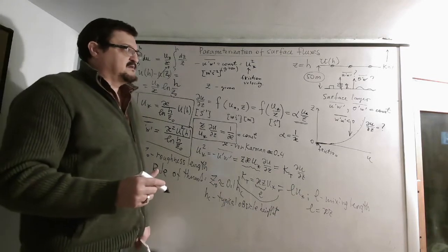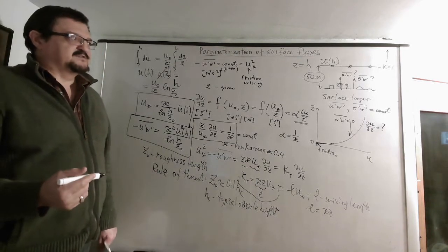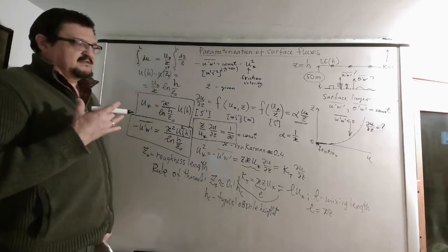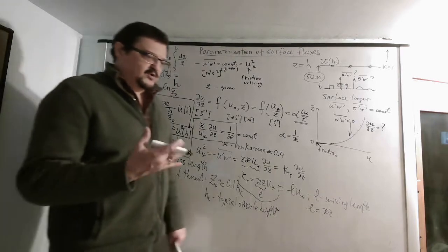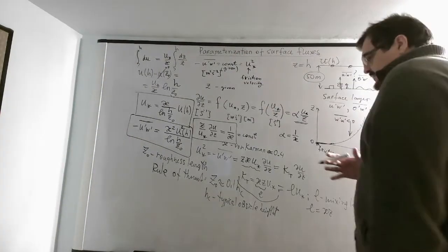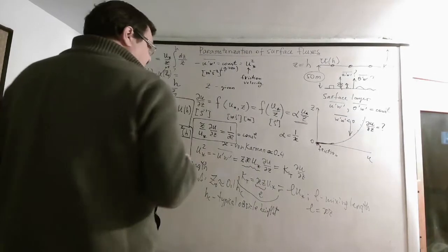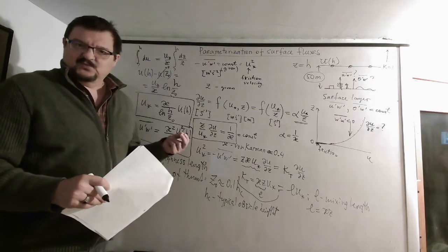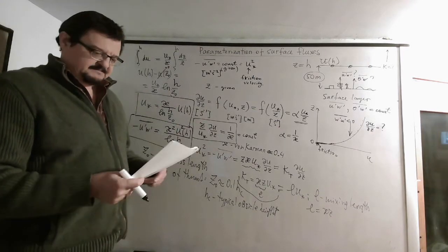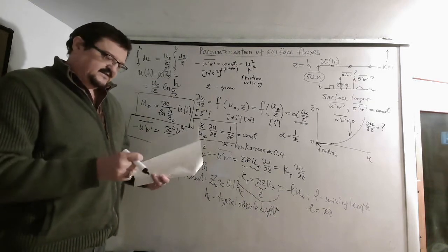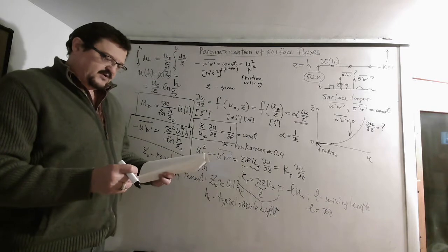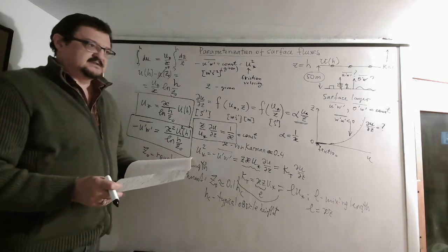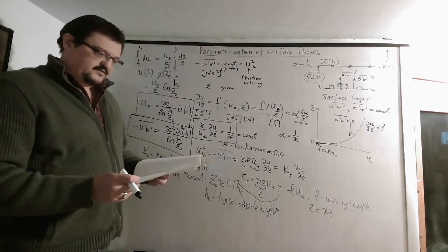So now there is one case when a different formula is used for z naught. Actually, z naught can be computed, and that case is a sea surface. When you have a water surface, lake or sea, and there is some wind over it, of course wind generates waves. And the height of waves should depend on wind, right? So when you have strong wind, the seas are rougher. So there is some correspondence between wind, so this friction velocity, and roughness length of the sea surface.